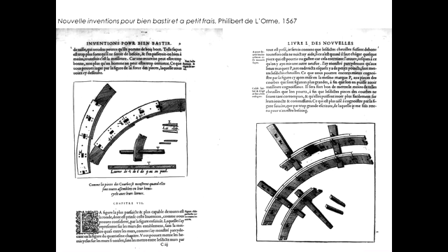But before that, just a curiosity. This is an ancient application or experiment to develop a composite timber product. So this is Philibert de l'Orme. We are in the 16th century. There is no glue, of course, because glulam means that there are two boards which are glued together, to make a longer element and a stronger element. So in this case, there are two timber boards which are connected with key elements that are literally working like nails.